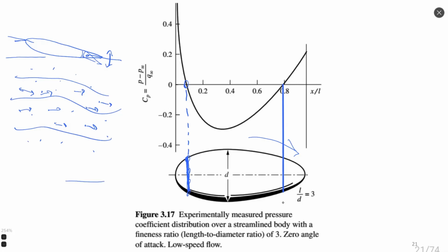For example, there is a ball sensor, like this ball sensor. Okay, it has a shape of a ball on a stick. And on this ball, we have several orifices, and each of these orifices is connected by a small pipe and measures pressure at this orifice on the sphere. It's a spherical sensor. It's not just two-dimensional, it can be a three-dimensional sensor.